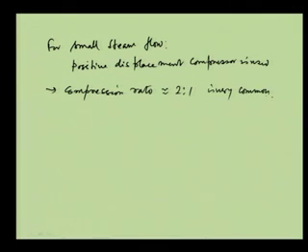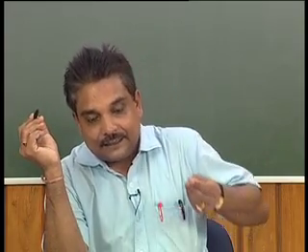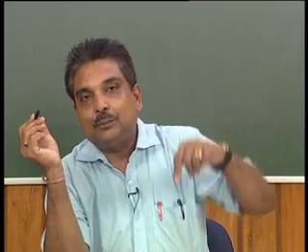What is meant is that a vapor recompression unit associated with a single effect evaporator sometimes works as an alternative to a multiple effect evaporator. In this case, the vapor which is coming is compressed and then recirculated back and put into the same evaporator.